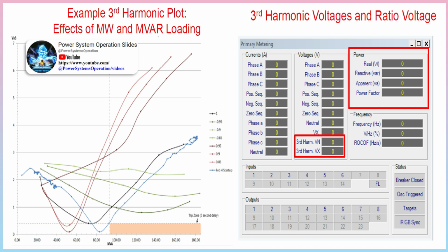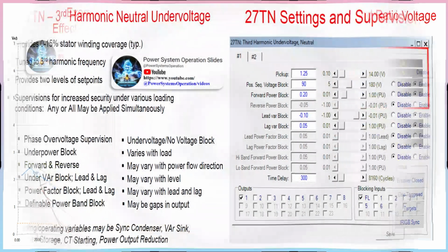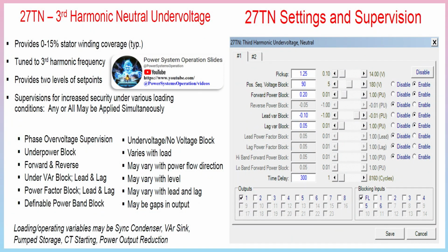Stator ground fault. Traditional stator ground fault protection schemes include neutral overvoltage and various third harmonic voltage dependent schemes. These exhibit sensitivity, security and clearing speed issues that may subject a generator to prolonged low-level ground faults that may evolve into damaging faults.